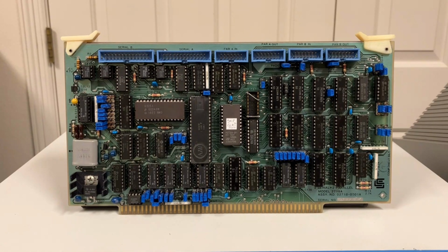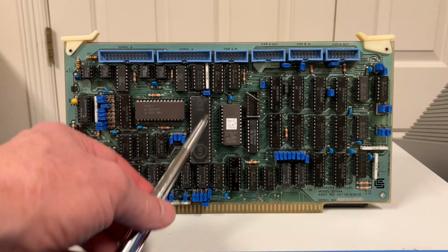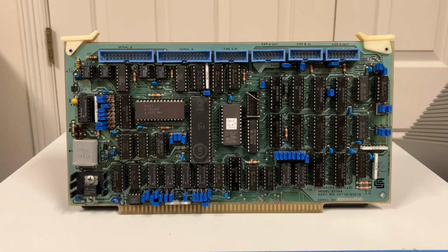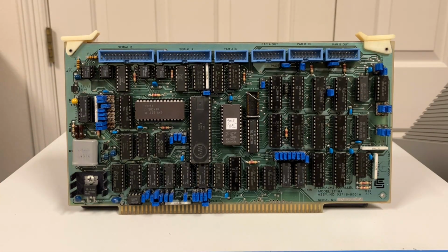All right, now we need 8 bits, no parity, 1 stop bit. That's done with these jumpers right here, which simply set the levels over here on pins on the UART. So that gives us our 8 and 1. We need 300 baud. That's done with the upper 4 jumpers here. So that's pretty easy to set to. And at that point, this board is ready to go as far as getting our serial interface working, and to make it look just like the cassette interface.